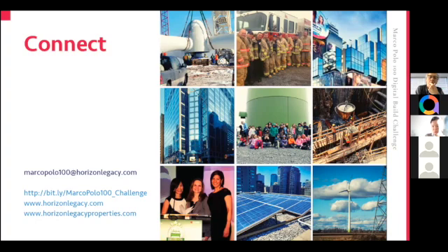I know what you're talking about, particularly where you have a right angle condition, right? You know, at the corner of the courtyard. What is the separation? Well, I know that there. Maybe diagonally. New York City code is kind of extensive and they cover a lot of issues that the international doesn't even go into. And this distance pertains just if you're looking out of a window directly out, that you don't have any obstructions in front of this window within the 30 feet of length.